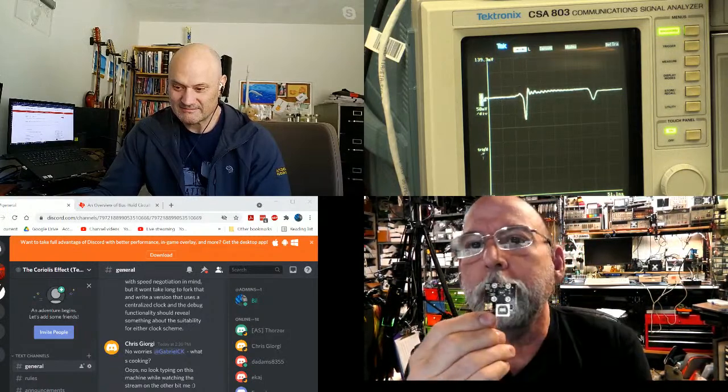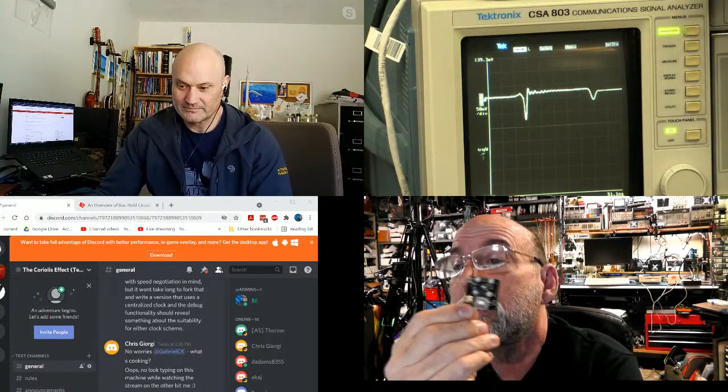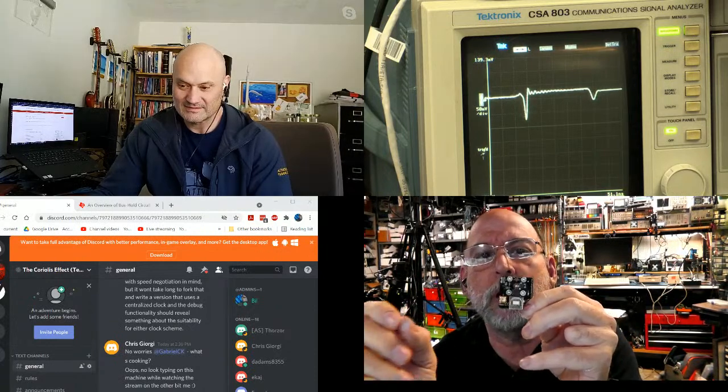So what's the SMA for versus the BNC connector? Which part of it's which? There's an SMA next to your USB port. The SMA is a trigger output, and you need that so your scope knows when the pulse occurred. So you would run the trigger output to your scope and trigger your scope on it, and then the BNC connector is the pulse and the reflection and everything you would measure. So where would you measure that? You would put a T-junction here, for example, so you could see the pulse go by and then return.